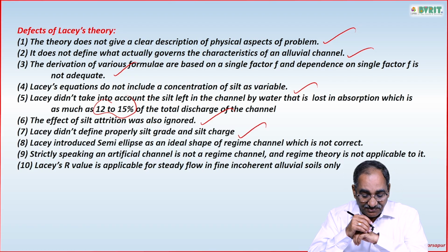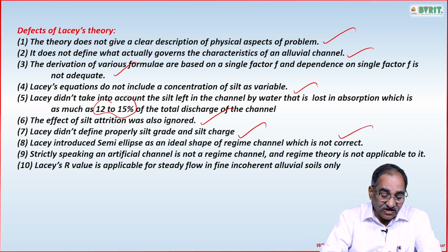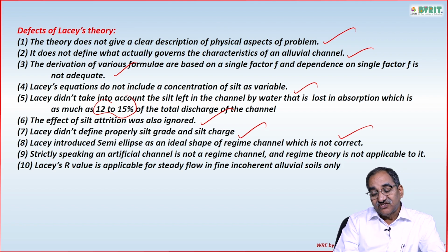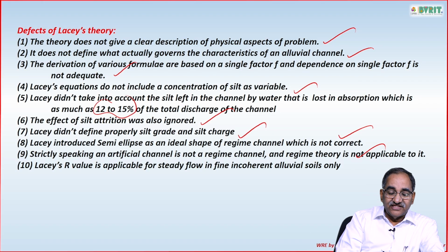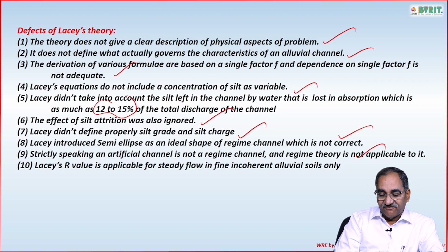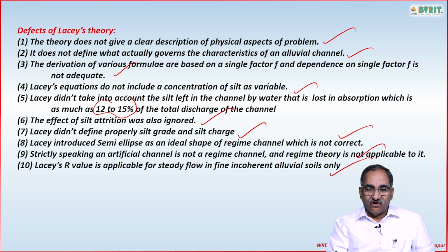Lacey introduced semi-ellipse as an ideal shape of the regime channel, which is doubtful. Strictly speaking, an artificial channel is not a regime channel, and regime theory is not completely applicable to it. Lacey's R value is applicable for steady flow only, that too through incoherent alluvial soils.